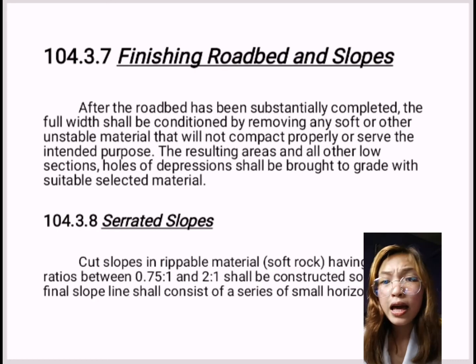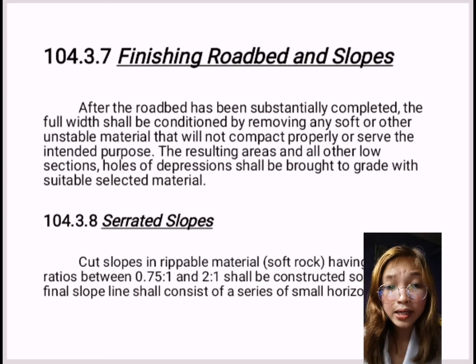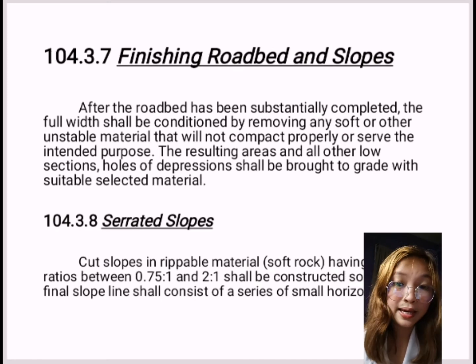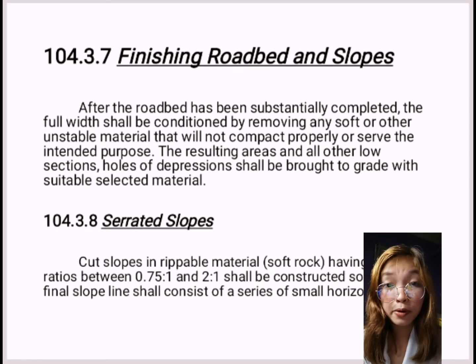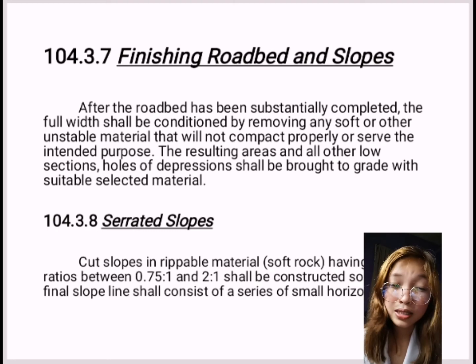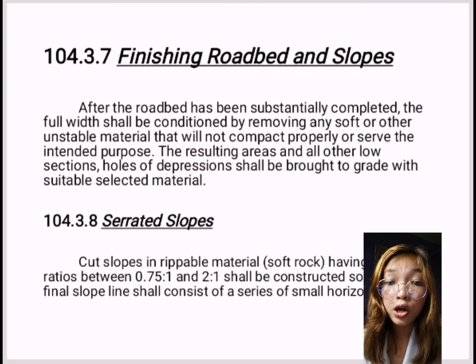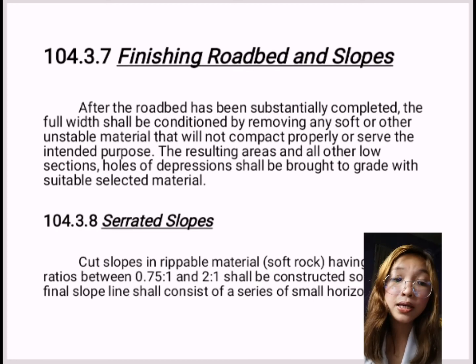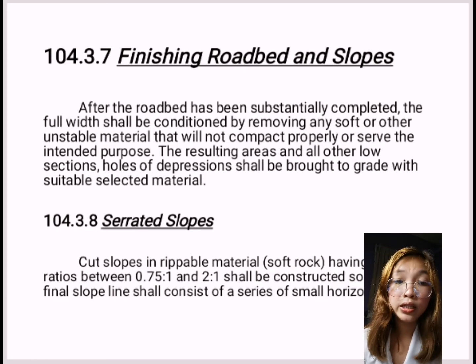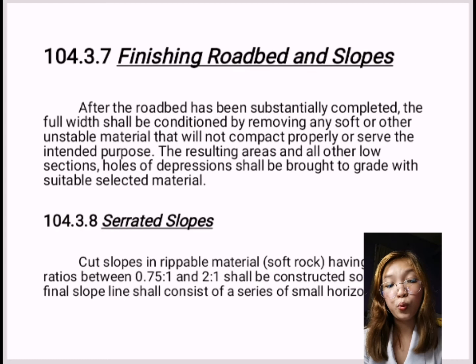So, the step rise and tread dimension shall be shown on the plan. So, no scaling shall be performed on the steep slopes except for removal of large rocks, which will obviously be a safety hazard if they fall into the ditch line or roadway.